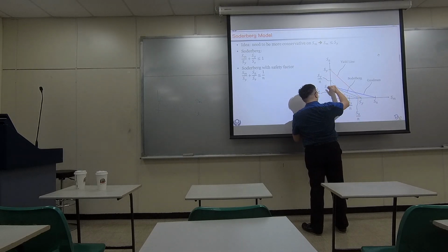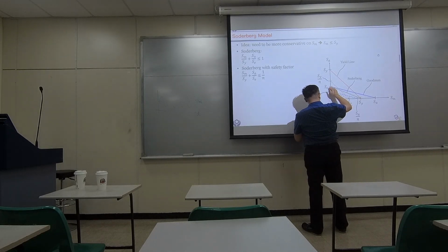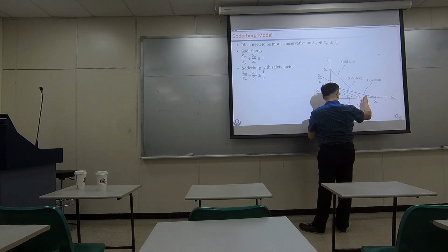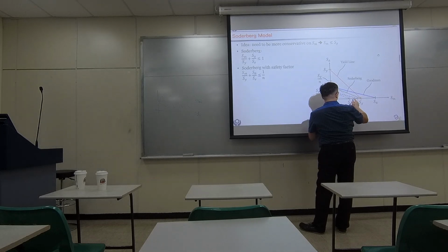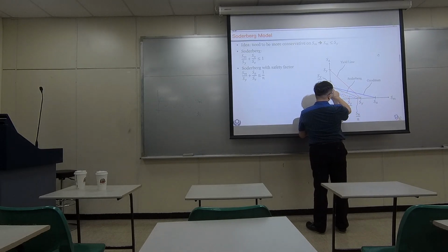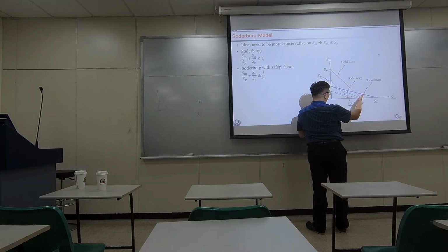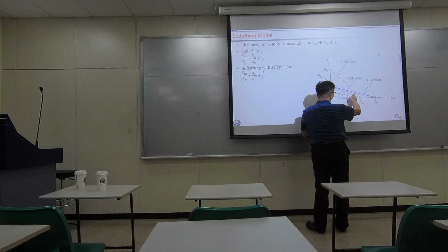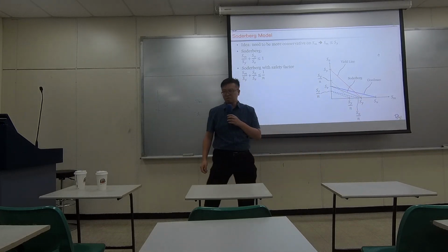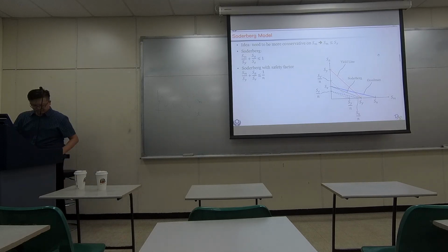So you are conservative on the dynamic part, the amplitude part, and also you can be a little bit more conservative on the mean value part. However, you do have an extra design space right here, like a triangular area that allows you to have more designs. And this area is less conservative than Soderberg. So if you Google modified Goodman, you'll see it.